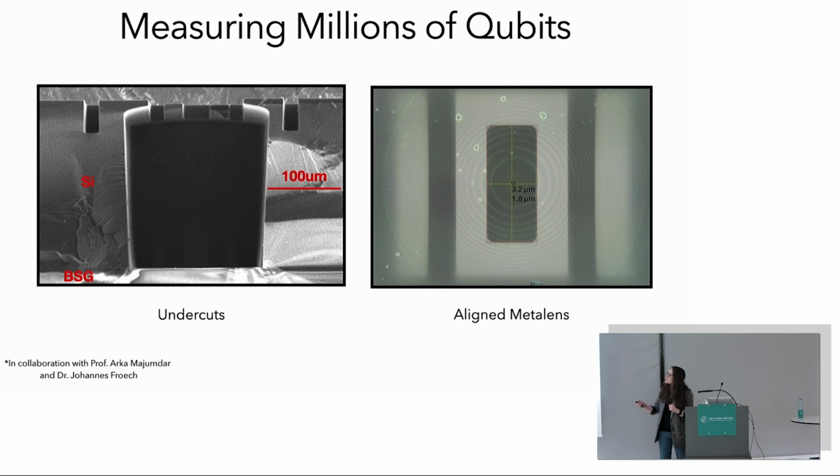And with this image here, you can see, so this is the middle ground electrode, and these are two RF electrodes. This is the space between the electrodes, and this is the slit over which the ion will be trapped. And these concentric circles, this is an overlaid image. These concentric circles are the metal lens that is fabricated on the bottom of this trap. Okay.